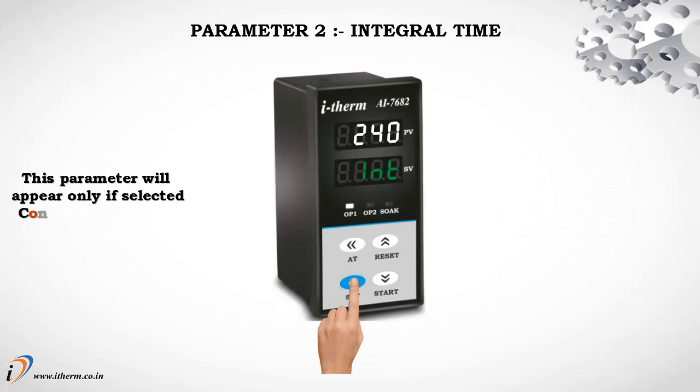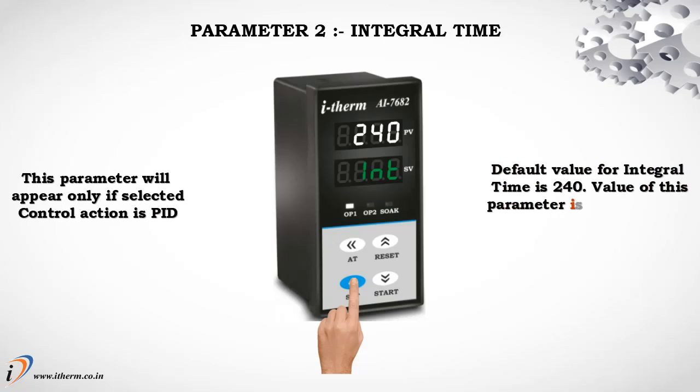Parameter 2, Integral Time. This parameter will appear only if selected control action is PID. Default value for integral time is 240. Value of this parameter is automatically set by auto-tune function.